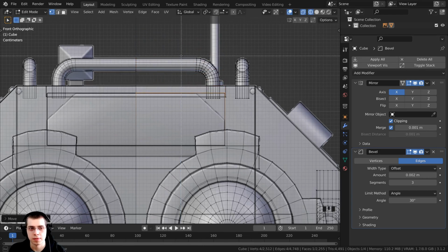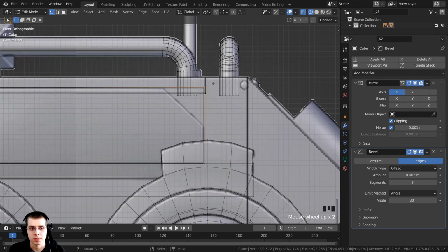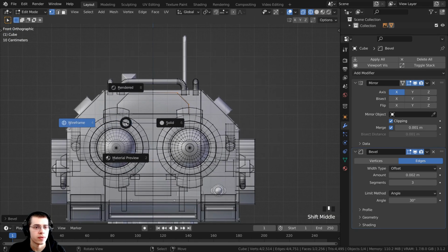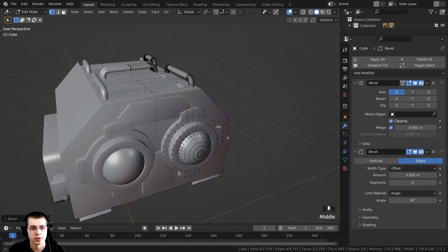And then I can press B for the box select, and again I'm going to click with my middle mouse wheel and just drag a box around those vertices and let go. That's going to deselect it, so now we just have those vertices selected. And then I want to add a bevel there. You can see there's kind of a bevel there. So I can just press Control B to add a bevel, and then I want it to be a very straight bevel. So after you press Control B, you can just scroll with your mouse wheel, and that's going to make there be less cuts. And then I can just fit that to the reference and place it right about there. All right, hold down the Z button, go back into solid view, and that's looking very good.